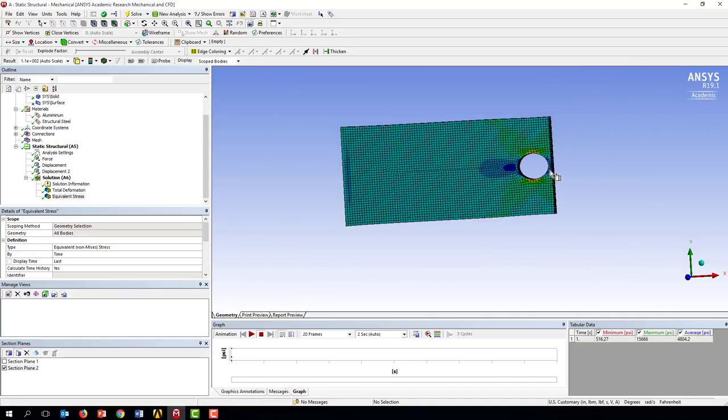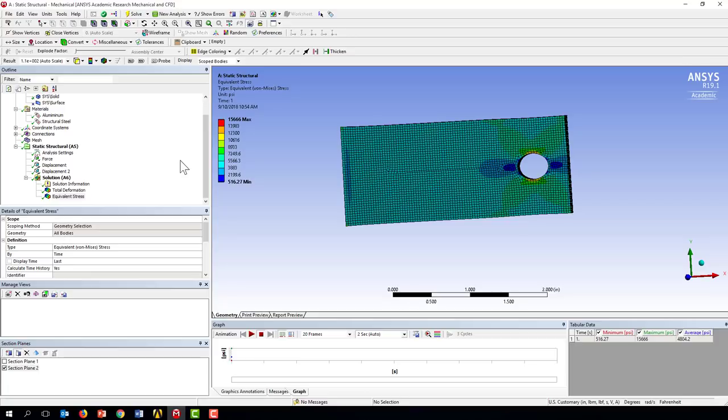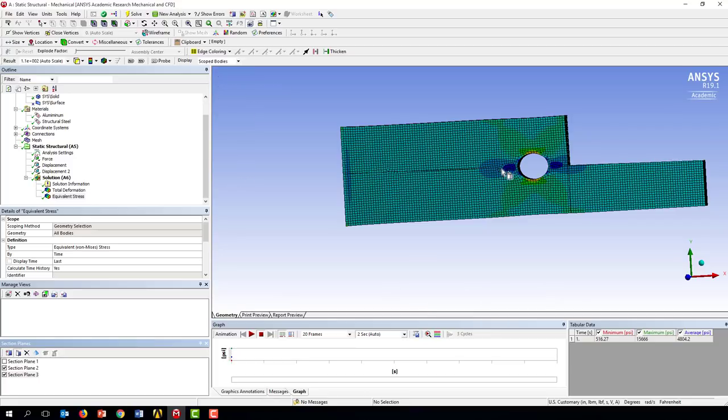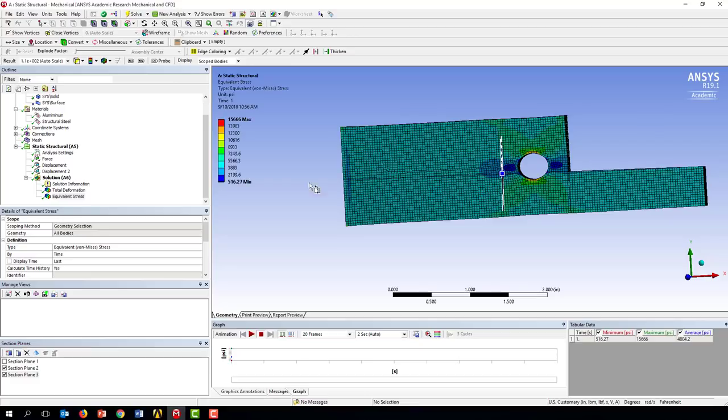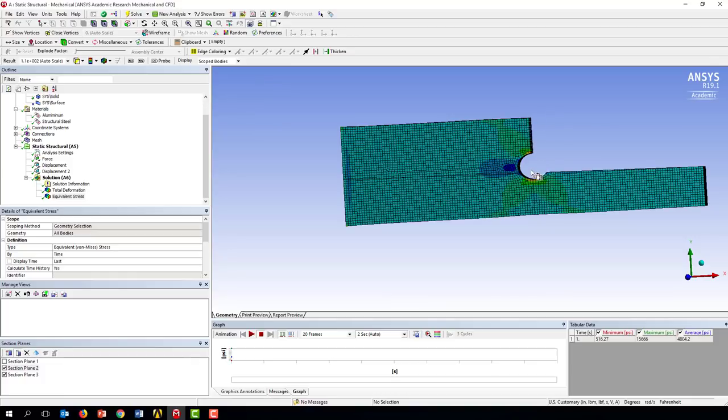All right, so that's one tool. And of course I could come over here and select define a new section plane and cut the other direction. And you can see you can have two of them operating simultaneously. So I click on this and edit section plane, and now I could drag this up and down where I'm cutting, and click over here, drag this left and right.